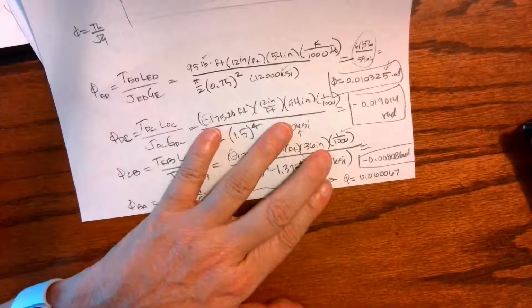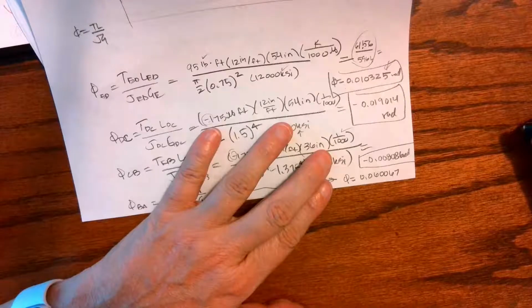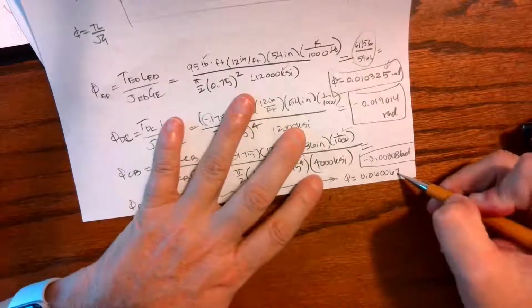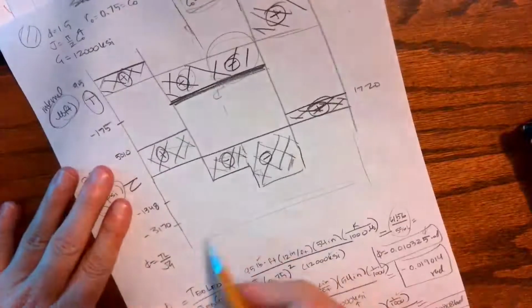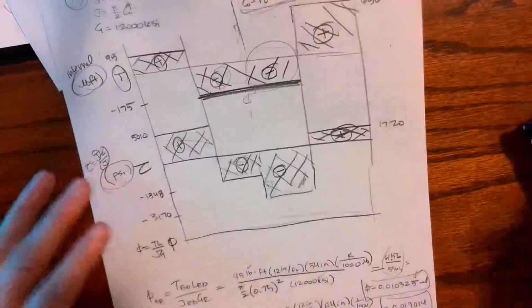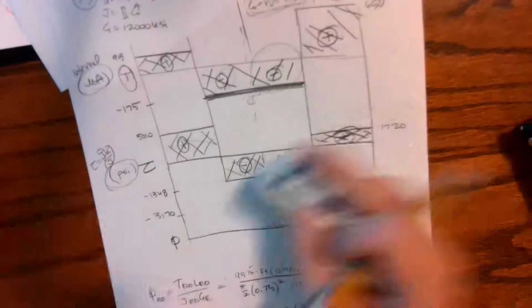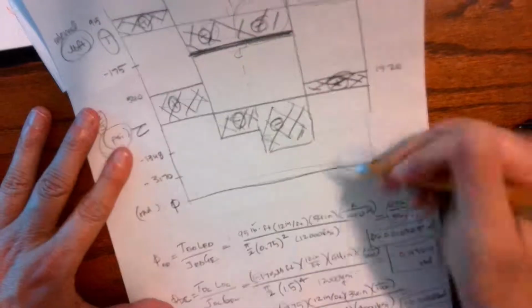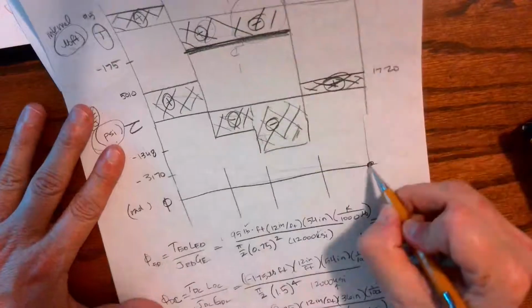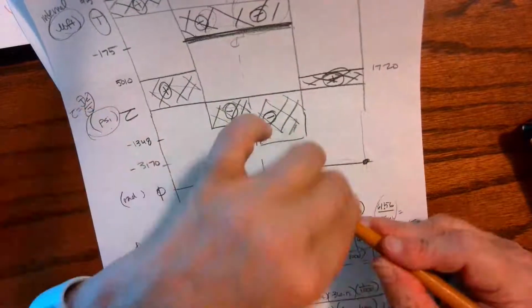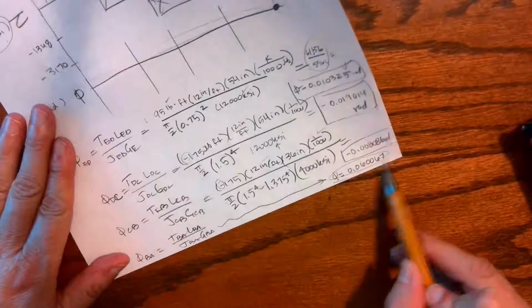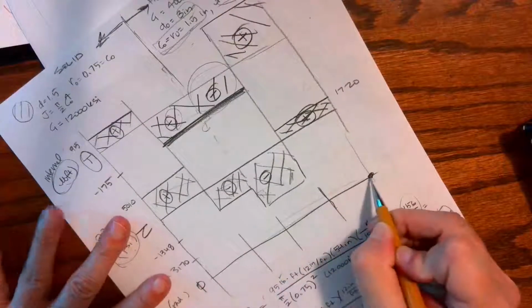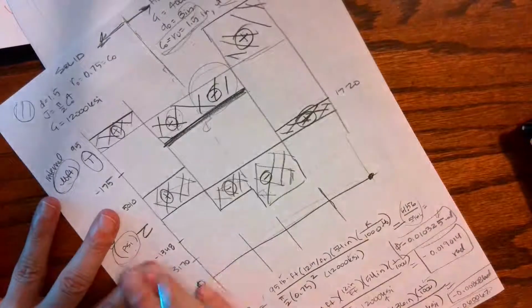So now, because I'm referencing everything back to A, everything with respect to A, I can draw a torque diagram. And my torque diagram is going to come from A back to the left. So if I start here, here's my phi, and by torque diagram I mean angle of twist, and my units are radians. So if everything is with respect to A, then I'm going to have 0 right here at A. That's our reference point. It says everything with respect to A.